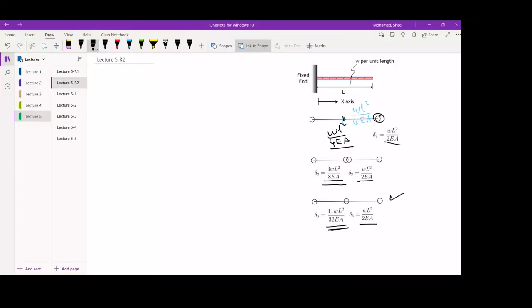Why we're getting the exact solution for this case, we said that always for the finite element methods, always at the nodes, we get the exact solution. I mean, even if it is a poor approximation, in general, you should be getting something exact at the nodes until you're really introducing some mistakes into the assumptions you're making. At the nodes, you should be getting the correct solution. Now, this is the case at this node, and this is the case at this node, and this is the end node also for the first element, or the first node at the second element. So we are also getting the exact solution at this node.